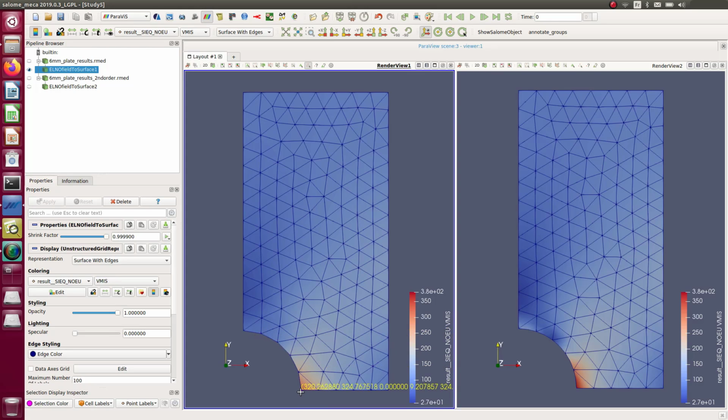The only one you have to look at is the first one. The reason is that this stress is given at the element, so it's a surfacic type of result, but it's averaged at the nodes, and the probe here in ParaView is only allowing me to view the result like that at the nodes.